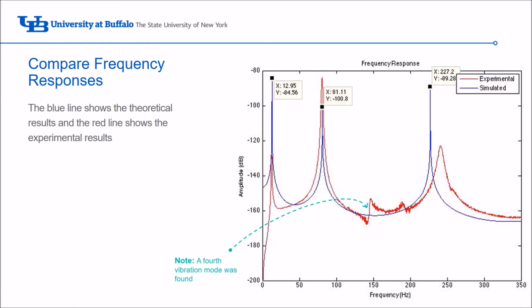Both frequency responses match each other well. It is important to note that during the experiment, a fourth mode was found. This fourth mode is the frequency at which the beam vibrates like it was a thin plate.